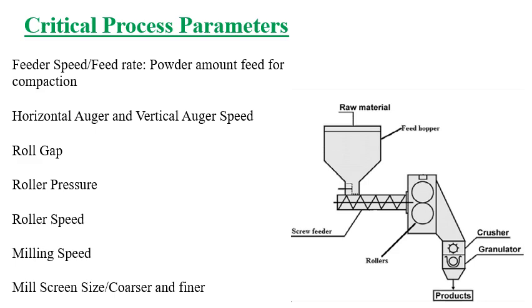Whenever the API is moisture sensitive, has a hygroscopic nature, is sensitive to water or may undergo hydrolysis due to the use of water, or is sensitive to heating and drying processes, then generally the roller compaction method, that is the dry granulation method using a roller compactor, is used.